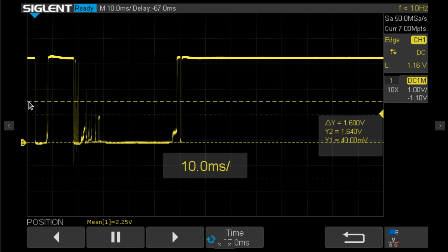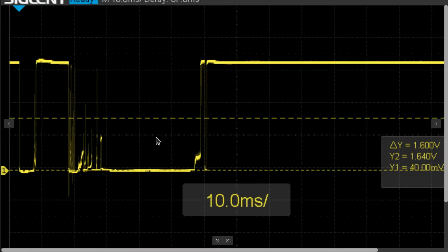Now this one in particular, electrically, has done us no favors at all. The raw switch is connected directly up to the FPGA. And by that I mean there's no capacitors or anything on the line to slow these little spikes down. I mean, you can do some work in the analog domain to clean up that signal if you really want to. I decided not to, because we can fix this to some degree in our FPGA, and that's what we're going to talk about today.